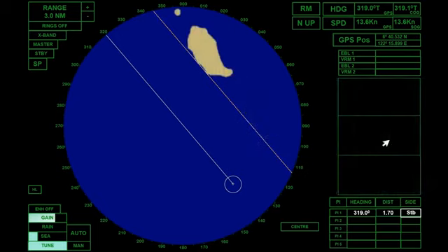However, knowing that the ship's position is on the planned track is not the only objective of the parallel indexing technique. Knowing that the ship is still in safe water even if she is not along the planned track is the primary objective of this navigation technique.